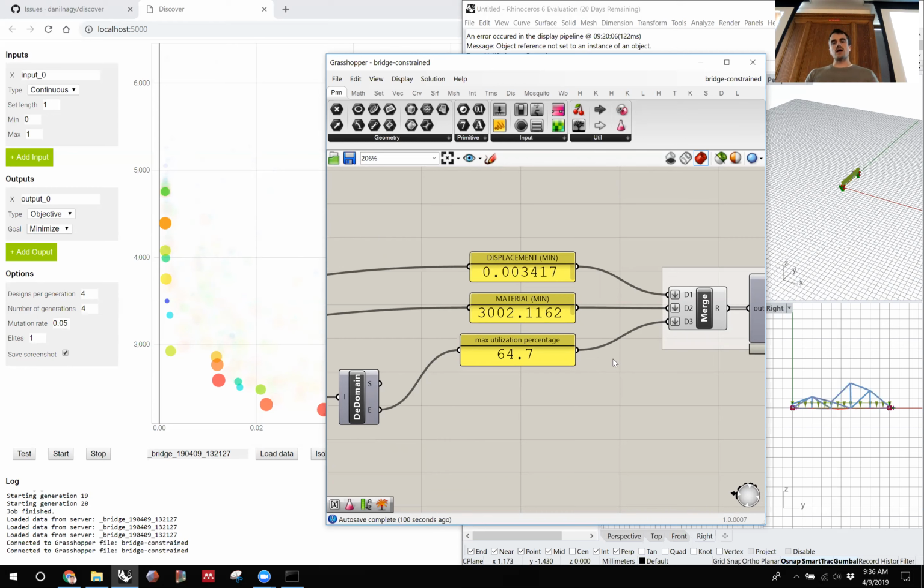And we establish the criteria of that constraint based on the safety factor we want to use. Right? So here, if it's telling us that the maximum stress in the structure is 64% of the maximum, that's related somehow to our safety factor. And the safety factor is basically the multiple of utilization that we're comfortable optimizing towards. So if we say, okay, we don't want the structure to break, you say, well, as long as that stays under 100%, then it shouldn't break, right? But remember, we're in a simulation. There's a lot of assumptions happening here. But typically with simulation, we never optimize for 100% capacity. We usually do a multiplier. So a safety factor of 2 means we're actually optimizing for half of the capacity. Right? So even if there's a small error in the simulation or something's not quite right, we're pretty sure that it's not going to result in the structure breaking.